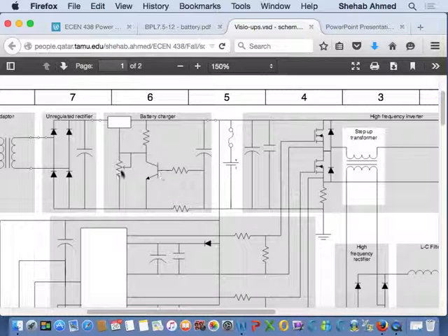And then there's a lot of other stuff that allows it to work, right? We said that the MOSFET, we talked about this last time, requires a power supply between the gate and the source to make it work, right? So this other stuff that we've added here is sort of this box that I drew last time as the power supply between the gate and the source that allows this block here to work as a linear regulator and supply the battery in a controlled fashion. In this case, I think we're putting 1 amp only through the battery, right?